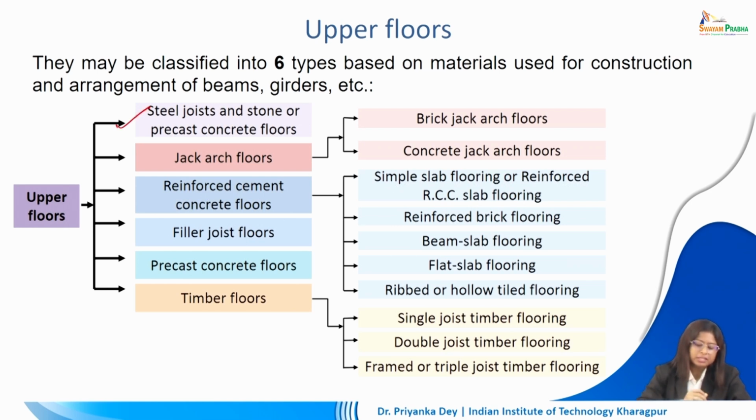We can use steel joists and stone or precast concrete floors. It's also possible for us to use jack arch floors. Jack arch floors can further be subdivided based on the material that is used. We can use brick jack arch floors and concrete jack arch floors. Reinforced cement concrete floors are also possible, in which case we can have several subtypes.